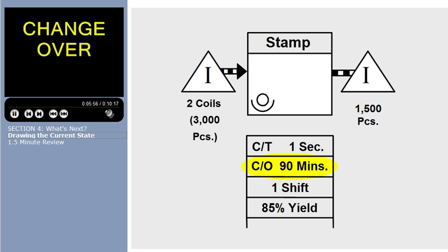Changeover is when a piece of equipment has to stop producing in order to be fitted for producing a different item. For example, the installation of a different processing tool in a metal working machine, a different color paint in a painting system, a new plastic resin and mold in an injection molding machine, loading different software, and so on. Changeover time specifies how long this takes.